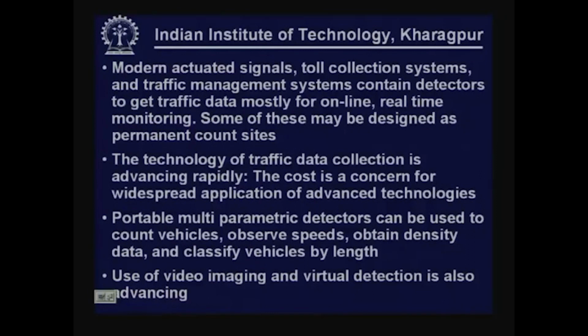Modern actuated signals, toll collection systems and traffic management systems contain detectors to get traffic data, mostly for online real time monitoring. Some of these may be designed as permanent count sites. So, the idea is that they are doing the traffic counting, but this is for online monitoring. It is not really working like a permanent count station. It is recording the data, but the purpose is different. Some of these places may be converted with a little bit of additional accessories and equipment to work as permanent count stations.